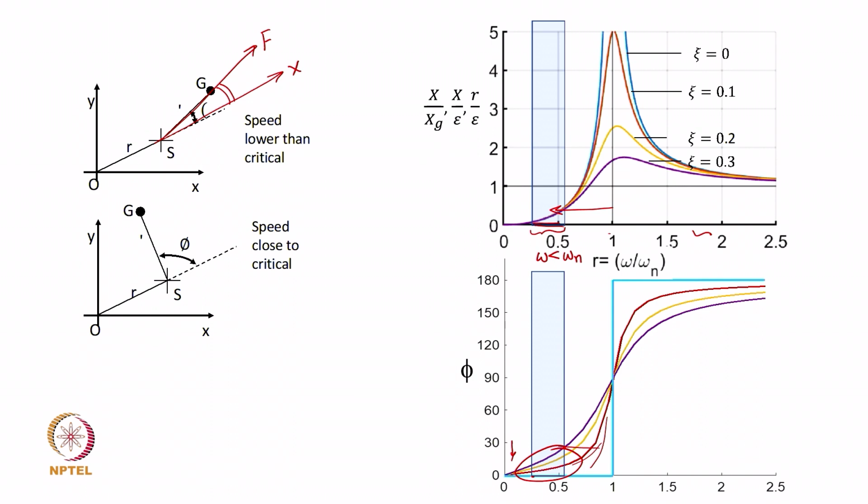And so, what happens is that if your rotor is spinning and whirling, as the shaft center whirls around the bearing axis, the mass center will be located outside of this circle, and the shaft is going to be lying here, and the mass will be flipped outside of that rotation and outside of that whirl circle.